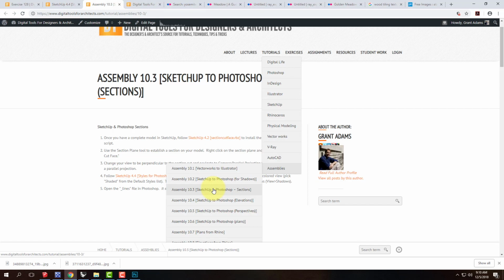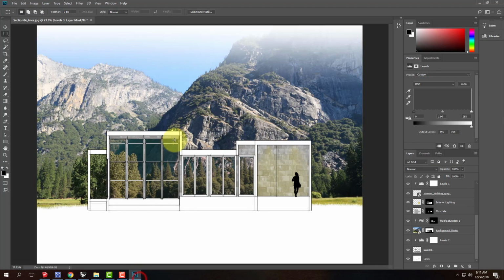If you want your Photoshop file to end up printing at a specific scale, I would bring the final version that we created today into Illustrator or InDesign, and do a scaling of that image based on the thickness of the roof or the thickness of a wall, and then it would start to become scaled at that point. But it would take some more steps to get this from being unscaled to being scaled. And so I like to kind of emphasize that as a point.